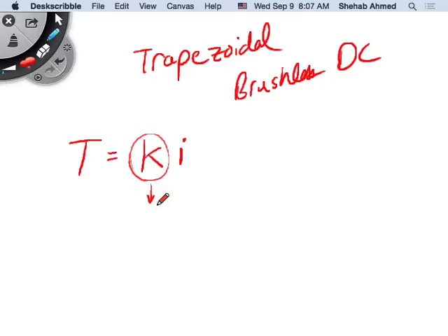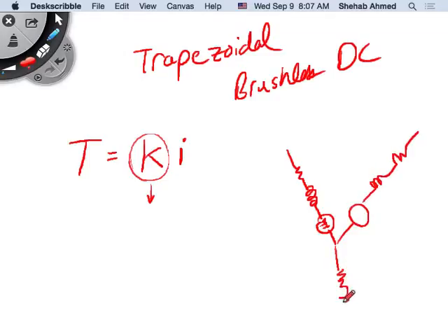Remember, we said that the back EMF is generated across a winding by this alternating flux. So the number of turns you have in series, the winding pattern, etc., will dictate how much back EMF is seen across a motor's winding. So a motor's winding can be represented simply as an R, an L, and a back EMF source. This is a variable DC source, depending on speed. So this is a simple representation for a brushless DC machine.